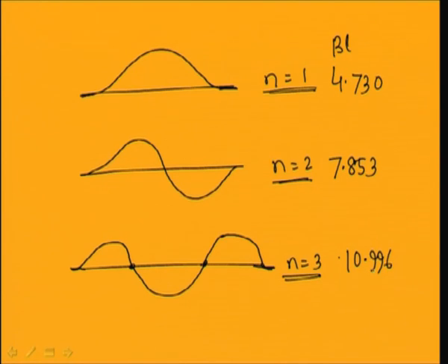You can similarly plot the fourth and fifth modes, and you can simulate to see the vibration of the fixed beam. As both ends are fixed, at these 2 ends the displacements are 0, and the slopes are also 0. Let us now see another boundary condition.